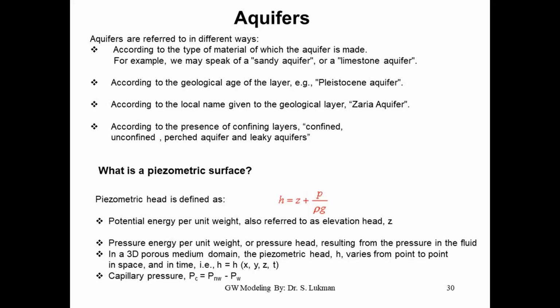So in the first part, when discussing the modeling part, we will look at the groundwater modeling aspect proper, in the sense that we are going to use ModFlow. Probably you all know ModFlow, the software, in which we will have some hypothetical aquifer or situation in which we have an aquifer, a pumping well, recharge, and all that at a particular rate, and then run it to see how the piezometric head is going to be affected over time.